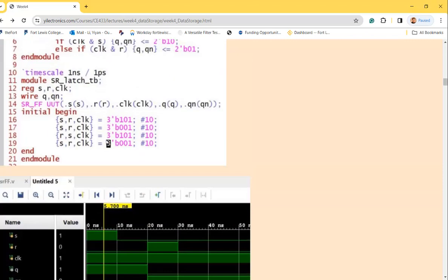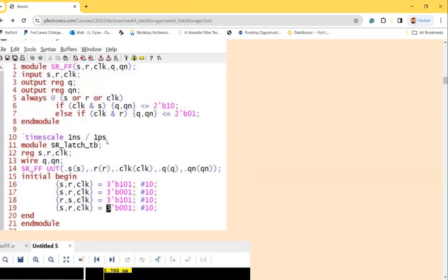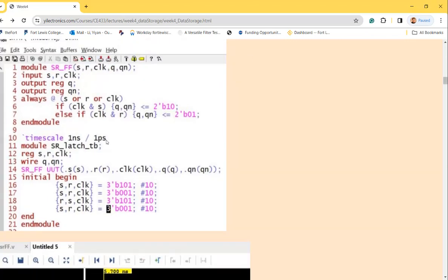Then how do you design a clock in your Verilog code? How to design the clock? You could definitely invert, flip a pin, the clock signal line, right, in a loop. But here I think it's just the 4 cycles, and clock is always 1. Because only when clock is 1, the AND gates are able to pass R and S to the latch. Otherwise, it's disabled.